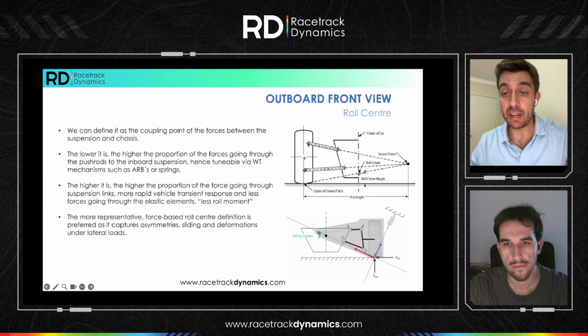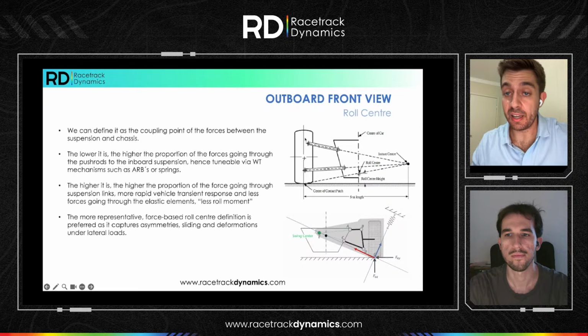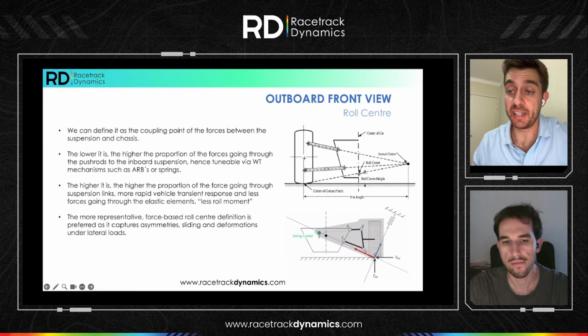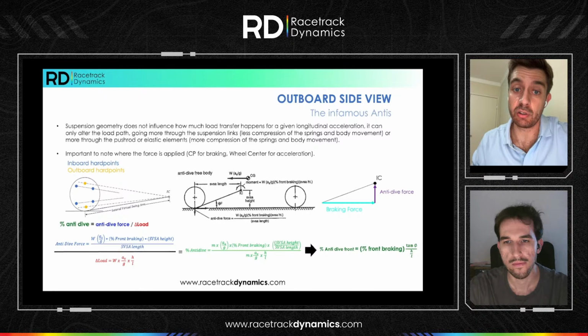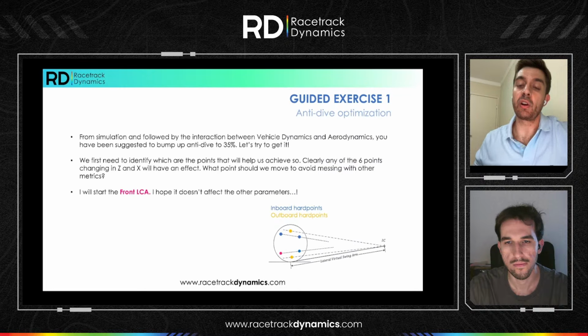I've raised it a little bit. So this element here is more inclined, and the instant center is a little bit closer to here, and then my roll center is a little bit higher. So these points cross much closer to the wheel center, and then the roll center height is higher. So this is what I've tried to do to recover my roll center height.